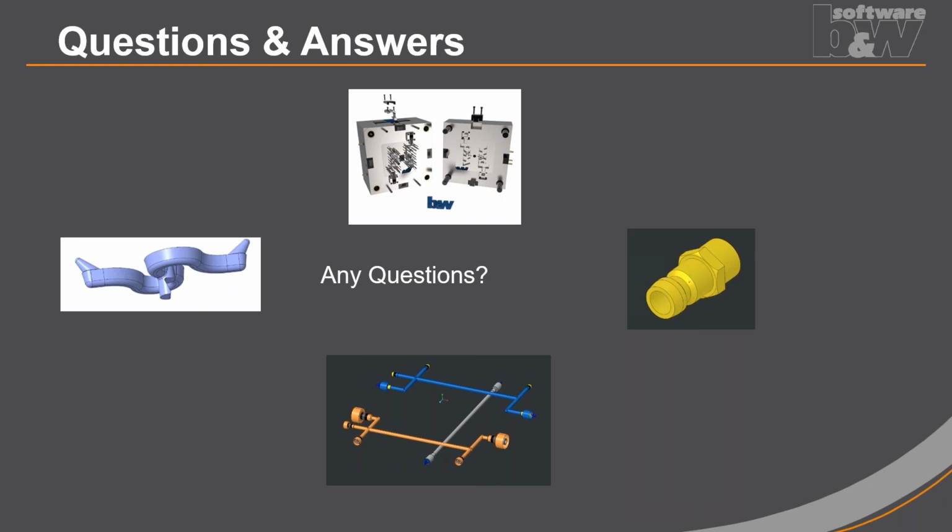The algorithm will recognize edges which are on the boundary from the UDF to the outer surfaces. So these edges will be recognized, but sometimes you will also need to add chamfers to edges which are within the UDF.